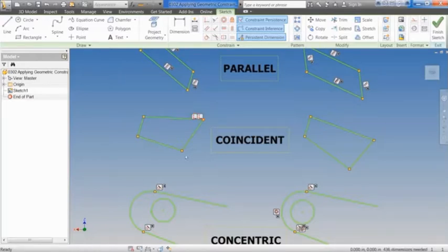Because of this, your sketch could get very crowded very quickly whenever you were trying to edit your geometric constraints. So instead, Inventor added this little yellow dot that, if you hover over and click on, will give you your coincident constraints. You can still move it around and see it. If I want to delete it, I can click on it and select delete, and it'll go away. It just collapses it down to make it a much more compact and easier to use glyph and not getting in your way all the time.